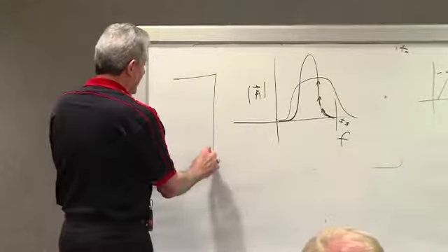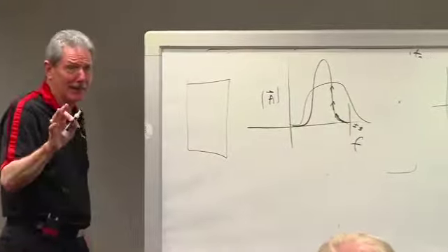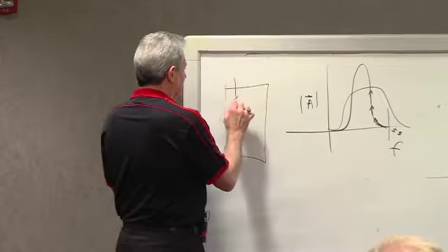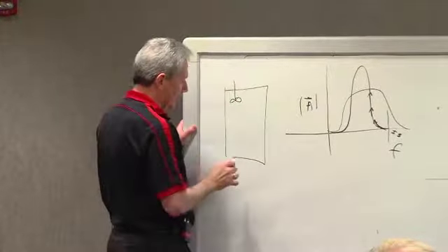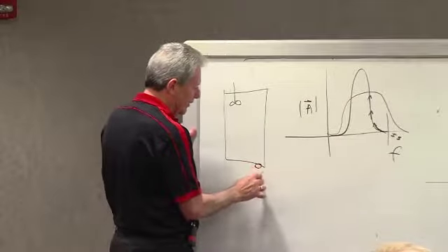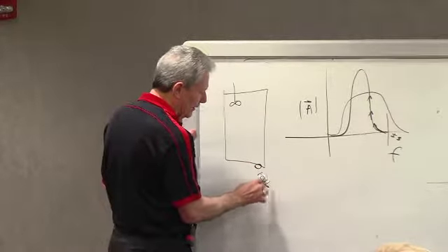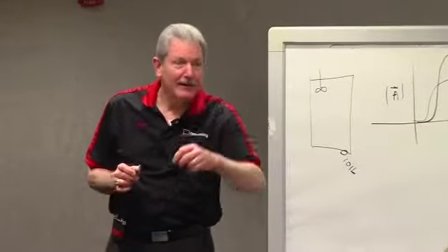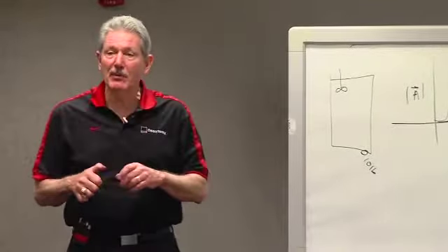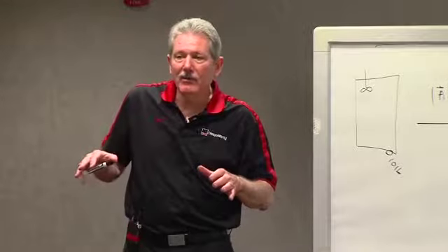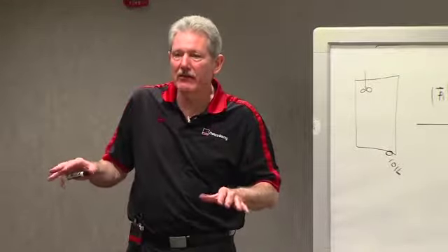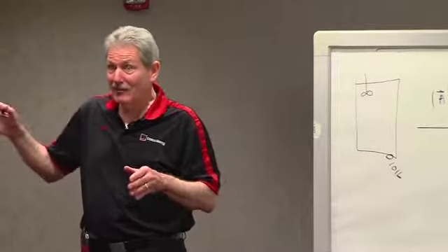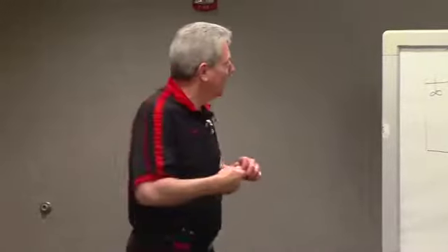Now we had a vehicle, and what I'm going to tell you is true. Here's the steering wheel. The first thing they did is they put a 10-pound bumper damper. Do you believe this? I believe it. All it did was lower the resonant frequency. It detuned the body. Back then, 10 pounds was a lot of money.